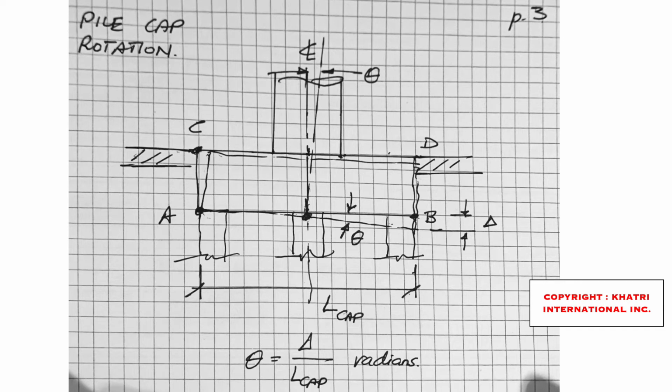Even though the analysis that I've done is a single portal frame, it's a simple frame, it applies to a multi-story structure just as well. It probably will show worse in a multi-story structure because you have multiple levels. But the principle, the structural principle that I'm driving home today is that deflections matter. They matter a lot. And they're not in the code, and they're not considered in design, and they're not part of our general practice of engineering.